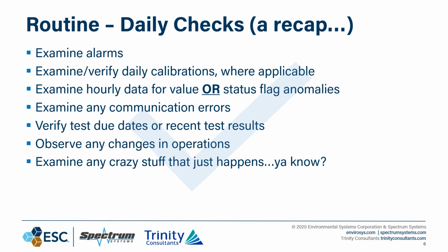Go ahead, Adam. Yeah, it never does. You're absolutely right. When CEMS goes haywire, it definitely takes a toll on your environmental reporting, the whole process. And so I'd like to point out that each of these daily checks are baked into what's called a CEMS QA/QC plan. So it's not just necessarily maintenance that you're scheduling out of your maintenance management system. It's these things that are actually regulatory requirements that should be in your CEMS QA/QC plan.